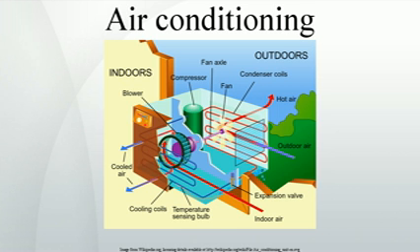Some homeowners elect to have a heat pump system installed, which is simply a central air conditioner with heat pump functionality. The refrigeration cycle can be reversed in cold weather. When the heat pump is in heating mode, the indoor evaporator coil switches roles and becomes the condenser coil, producing heat. The outdoor condenser unit also switches roles to serve as the evaporator, and discharges cold air, colder than the ambient outdoor air. Heat pumps are more popular in milder winter climates where the temperature is frequently in the range of 40-55 °F, 4-13 °C, because heat pumps become inefficient in more extreme cold.